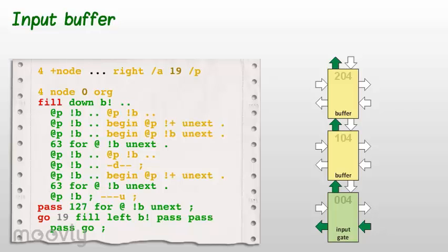Another feature of the presented code is a repeated use of fragment fetch_p store_b ... This piece of code starts at a word boundary and occupies one instruction word. We need to use a dot, which translates into no operation, in order to always align the compiled code to word boundary. When executed, the code reads the following word from node's RAM and stores it where register B is pointing. Since register B has been initialized at the beginning of word fill to point to down port, words read by this fragment are sent to node 104.